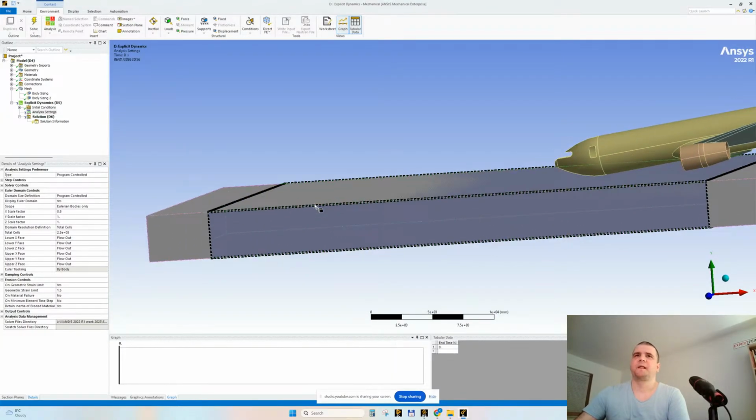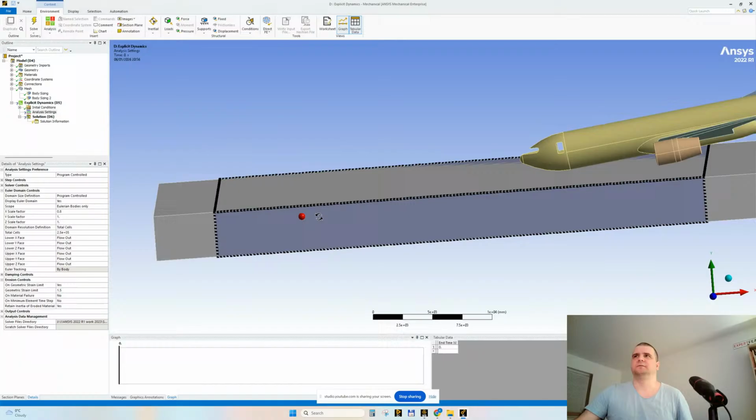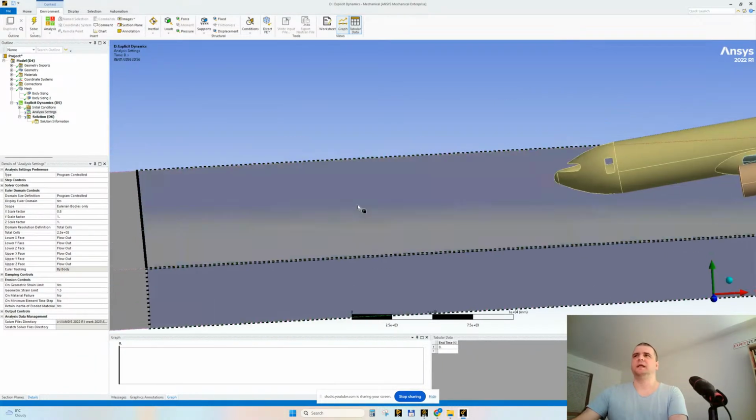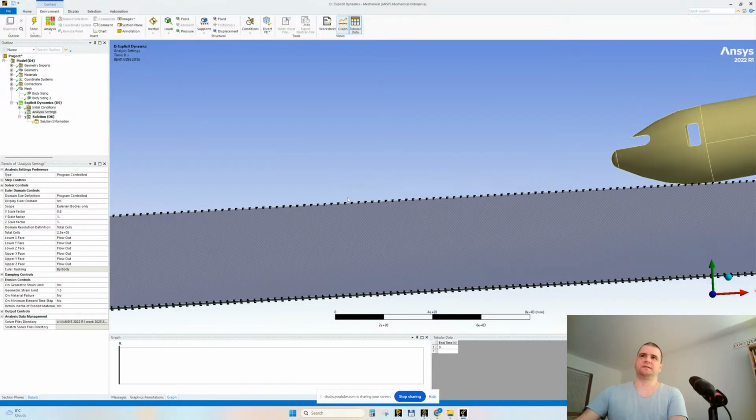If there is like a small dilemma or a small question that appears now. At this moment, you know what, let's leave everything like this. But if waves will appear, they will clearly exceed this limit, all right? If there will be waves. And because they exceed the Eulerian frame, we cannot see those waves. We can solve this by increasing the Y scale to, I don't know, maybe 1.05.